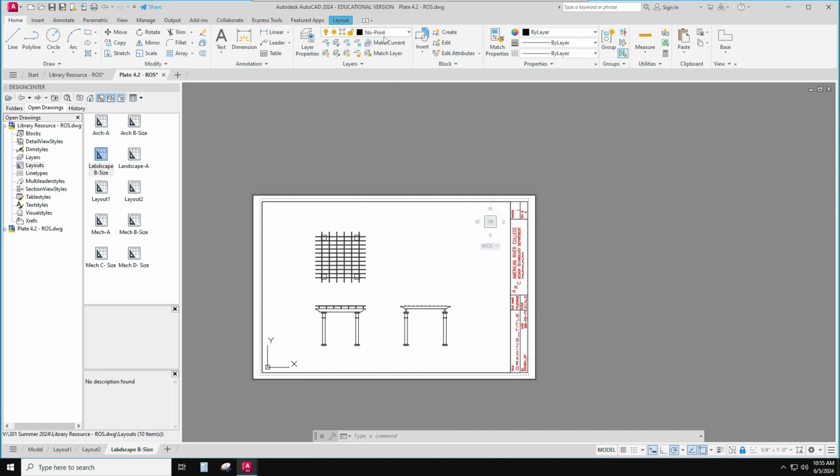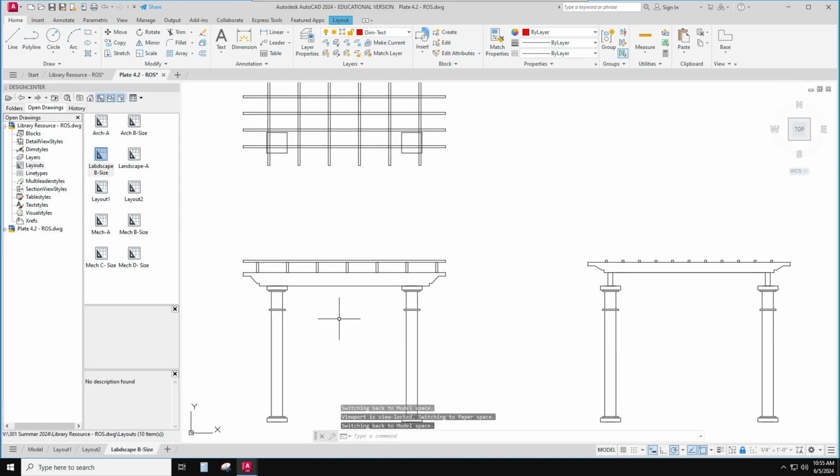And now the rest of it is you just putting in on the dim text layer all those things that we were looking at. Make sure now that you go to your piece of paper. And let's take our leaders. Let's see how big the leader is. I may need to make a leader style.